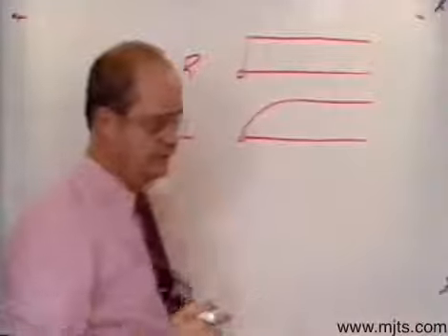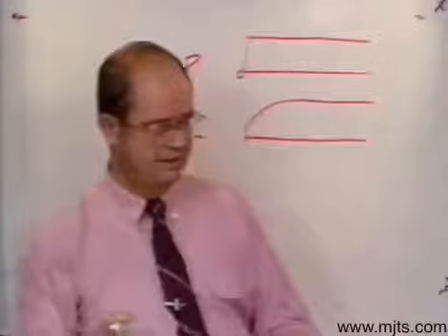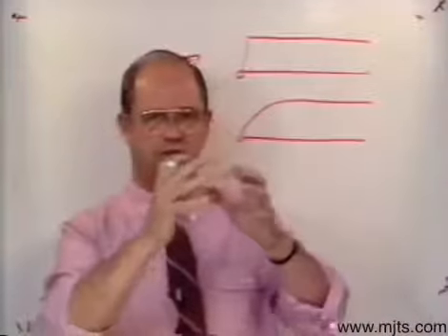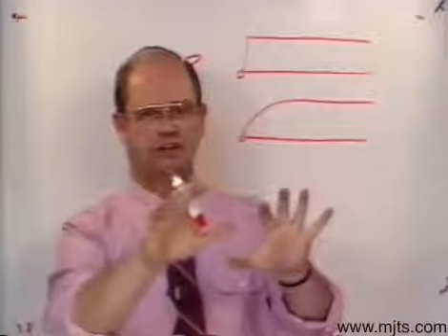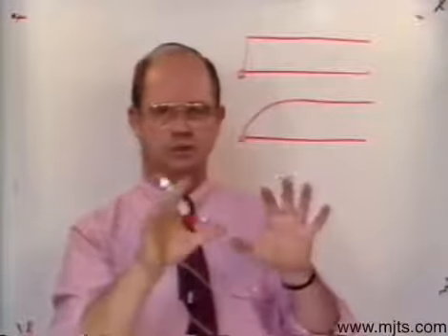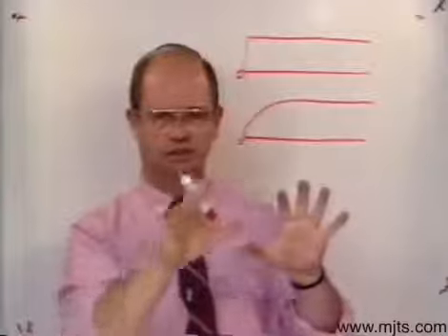Now, that inductor, you see, when we get a changing magnetic field, it's inducing back on itself. It's holding back any change that the current flow is trying to make. It can't go to the maximum because it's going to induce a counter electromotive force to oppose that.